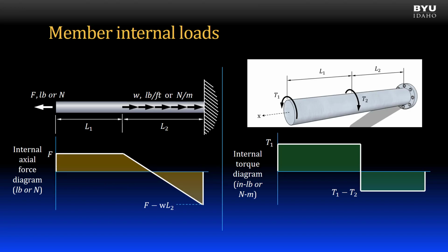First, a little background. Prior to beams, we learned about axially loaded members and torsionally loaded members. With both of these types of loading conditions, it was sometimes useful to plot the internal axial force or internal torque in a graphical form, or write them as functions of distance. In both cases, there was only a single internal load, internal axial force or internal torque. In both cases, the internal loads were equal to the accumulated sum of the external load.